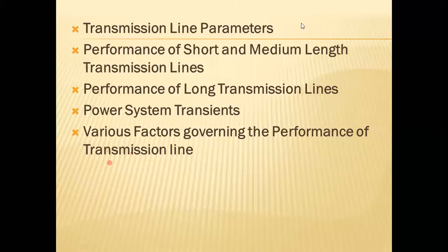When we discuss corona, we'll be discussing the phenomenon, visual critical voltage, disruptive critical voltage, and the factors associated with corona, radio interference.